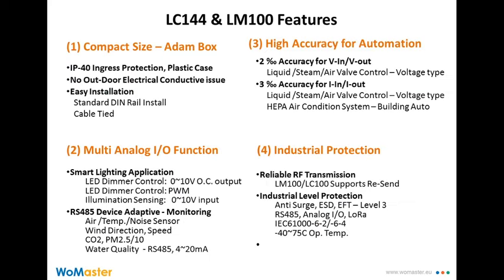In this page, we talk about some features. First, the outlooking is with a plastic case to reduce electronic interference, and the compact size IP40 I just mentioned, and the DIN rail style is easy to install. We also provide many ways of I/Os related to the different applications like the analog I/O, PWM, and the most typical way, RS485.